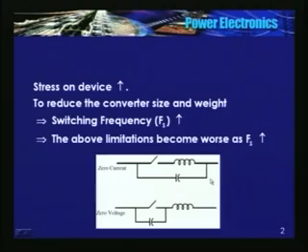So using separate L and C, it is now possible to reduce the switching losses and reduce the device stress. What do I need to do this? The existing power electronic converter now should have additional L and C circuits, that is all. The size of this L and C is really very small. So if I have to summarize, what are the advantages?